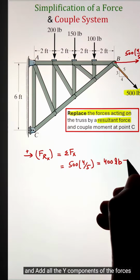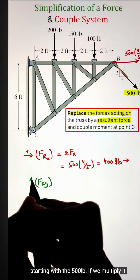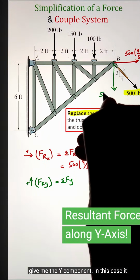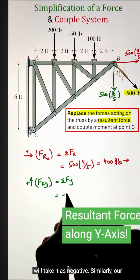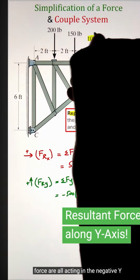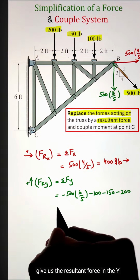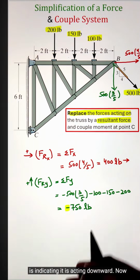Next, we can go ahead and add all the y components of the forces acting on the truss. In this case, starting with the 500 pound, if we multiply it by 3 over 5, it is going to give me the y component. In this case, it is pointing downward, so that's why we will take it as negative. Similarly, our 100 pound force, 150 pound force, and 200 pound force are all acting in the negative y direction. So adding them all together gives us the resultant force in the y direction as negative 750. Here the negative sign is indicating it is acting downward.